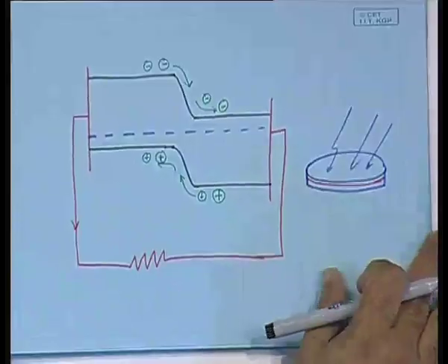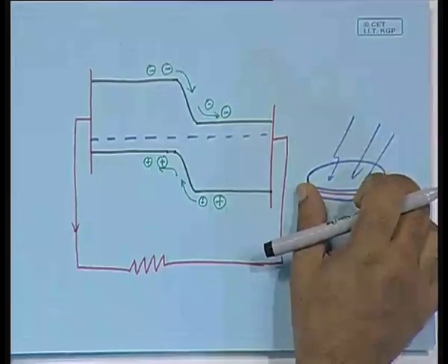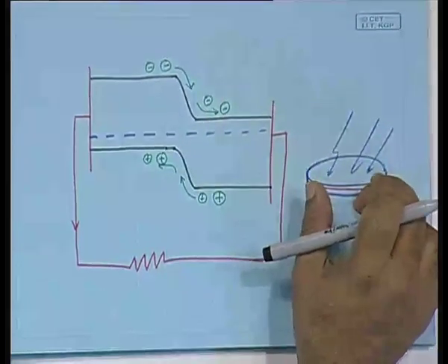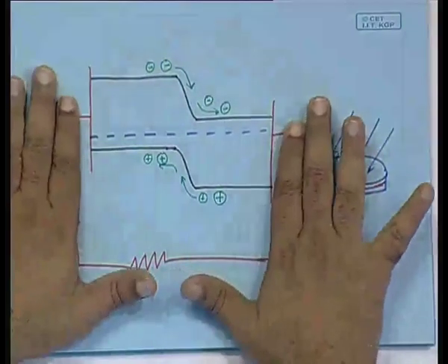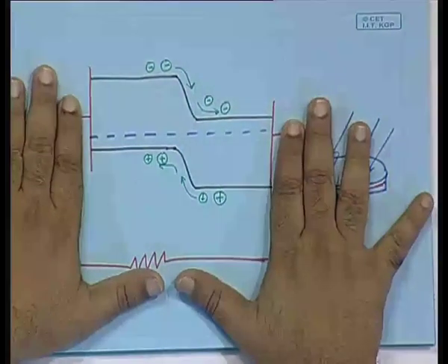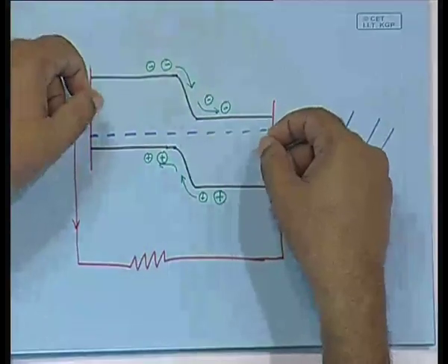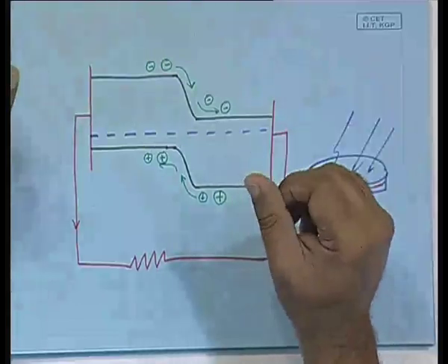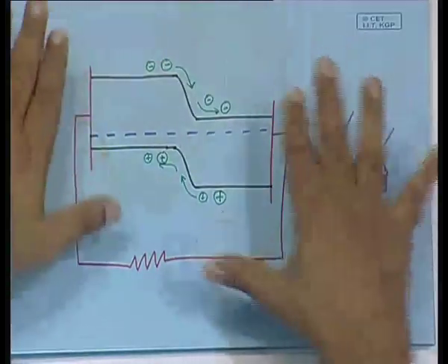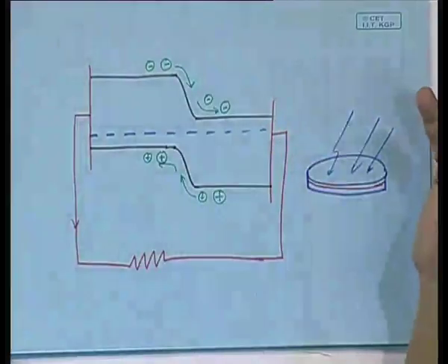Okay. Now, what happens? You have got after all the p-n junction, and the p-n junction implies that it is a diode. So, what will happen if say you do not connect anything? If you do not connect anything, then there will be a voltage difference, and the voltage difference will produce a current through the diode. A forward bias current is through the diode. See, it is a p-n junction where this is positive, this is negative, it is forward biased.